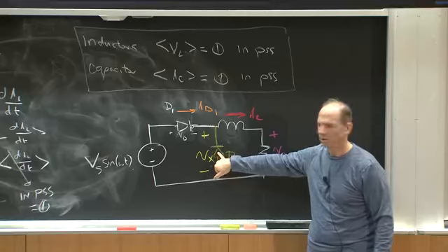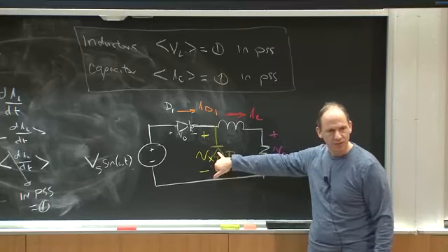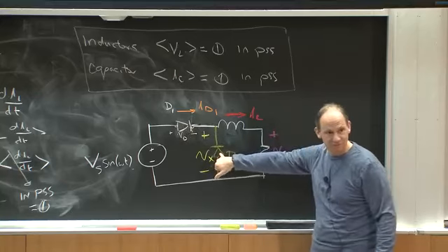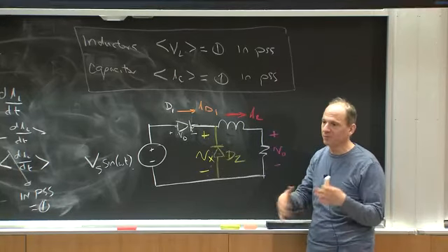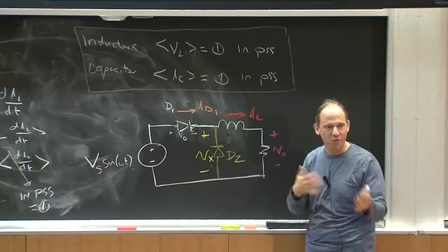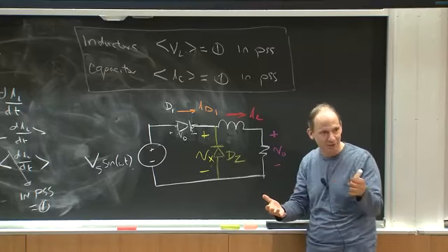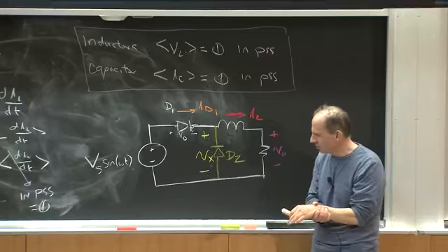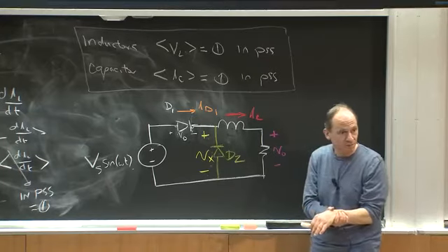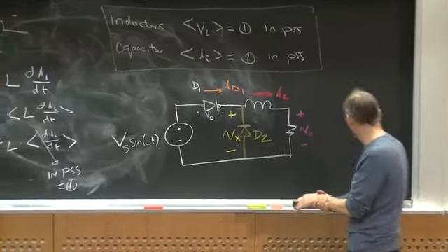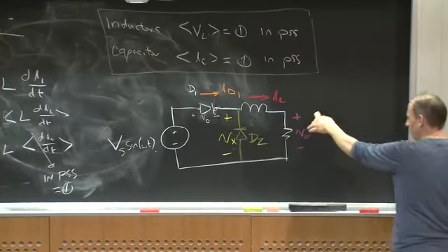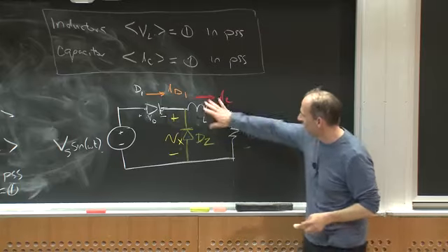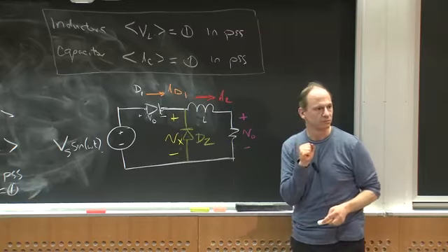All right? Well, how would I analyze this circuit? Well, I can do the method of assumed states. But now I have 2 switches, right, which could give me, in theory, up to 4 possible states, right? Both off, one on, the other off, the other on, both on, okay? But if I'm clever, maybe I assume that they're not both on at the same time, typically, or off at the same time, hopefully. And let me just assume the inductor is pretty big so that IL is going to be approximately constant, okay?